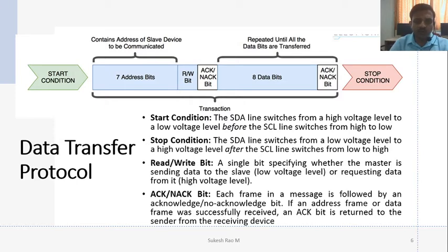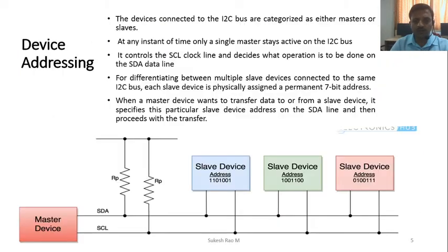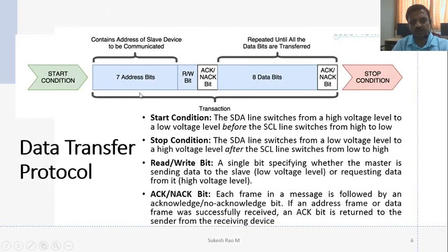Once you send that information, the device will respond here. For example, if you want to read the slave device, you send the start condition, then the 7-bit address, that is 69, and then the read bit, saying you want to read the device. Then immediately comes the acknowledgement. The white and blue highlights show what the master is sending and what is the response.